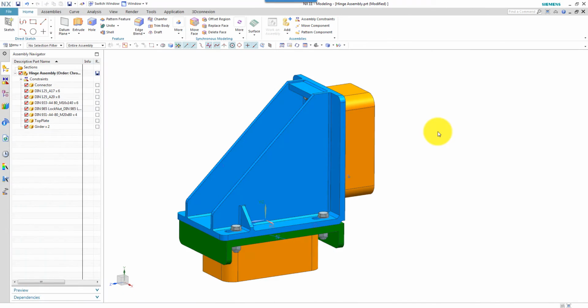Then I will show you the best practice way to create a mesh of an assembly like this. What I have to do then is to mesh first all the individual parts. And in this example, I don't want to mesh every part. Therefore, I will deactivate the bolts, which I will mesh on the assembly level as bolt FEM models or bolt elements.